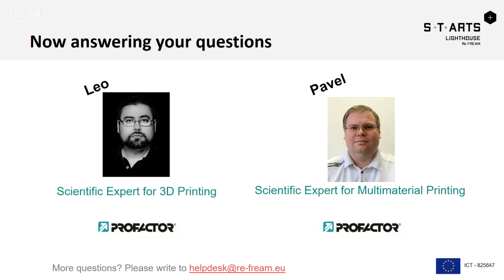What particle size is allowed? Pavel, you know by heart? Yeah, it's in the range of hundreds of nanometers, because the nozzle diameter is tens of microns, and the particle should be at least 10 times smaller. Also the particles should not agglomerate, so as not to create big clusters, because clusters can clog the nozzle.